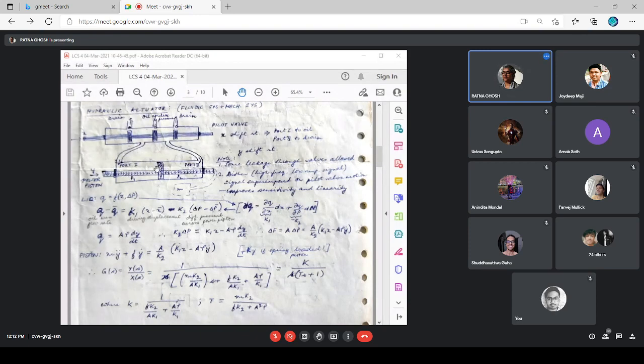Oil flow rate will be balanced by the pressure differential. So this pressure differential will try to restore it so that this oil flow rate goes down to zero. It's a restorative function. So hence this is negatively impacted, and this is minus K2. For our purpose here, since we are considering small changes, at the first step we are considering K1 and K2 to be constants.